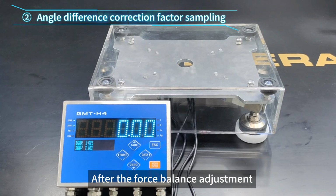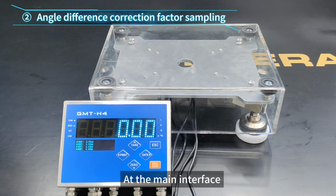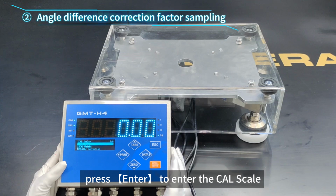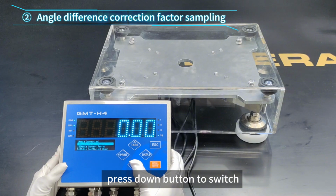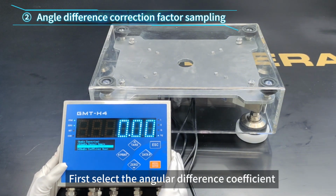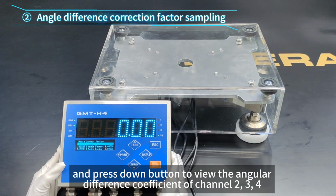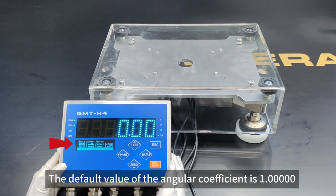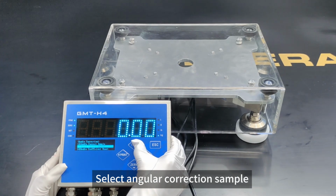After the force balance adjustment, we can enter the process of angle difference correction factor sampling. At the main interface, press Enter to enter the calibration scale. Press the down button to select the angular correction. Press the down button to switch. First, select the angular difference coefficient. Press Enter to check the value, and press the down button to view the angular difference coefficient of channel 2, 3, 4. The default value of the angular coefficient is 1. Press ESC to return. Select angular correction sample.